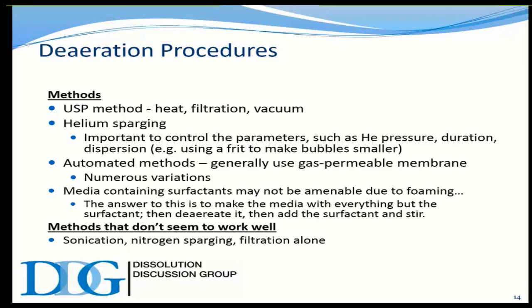So de-aerating 50 liters of media with a very effective technique, which is helium, can be a bit cost prohibitive. We'll spend a little bit more time talking about helium, but it is a good means of removing air. You're just sparging it, replacing it with a very tiny molecule. So it is quite effective.